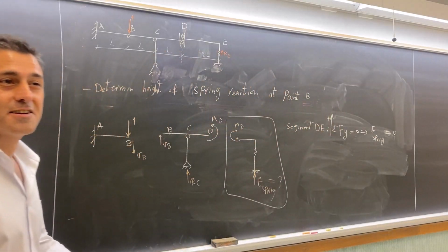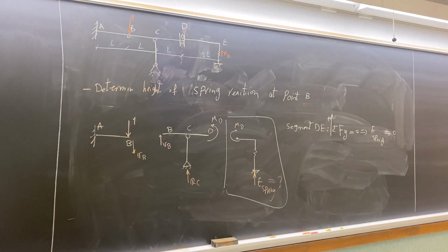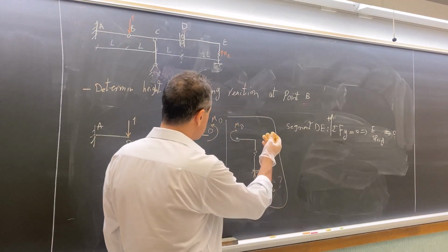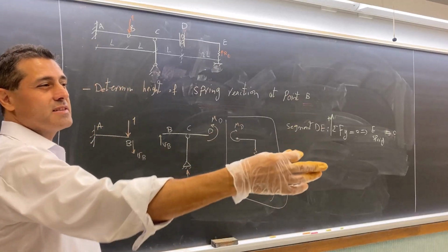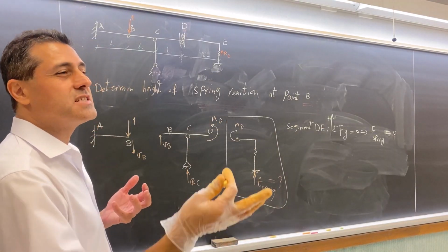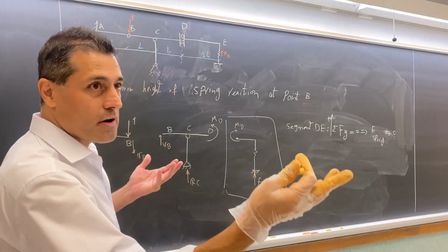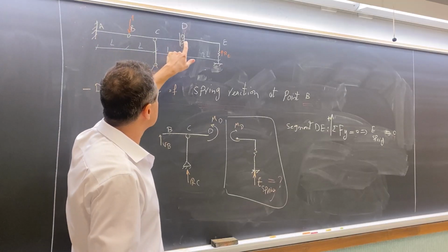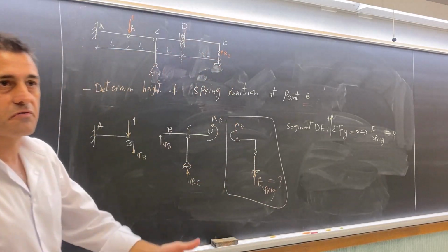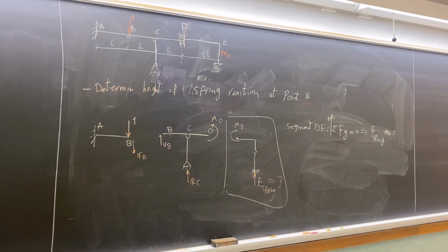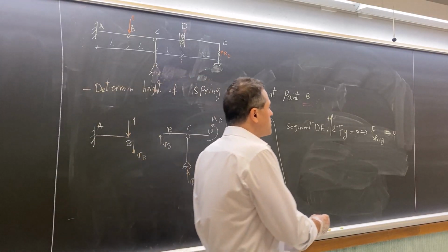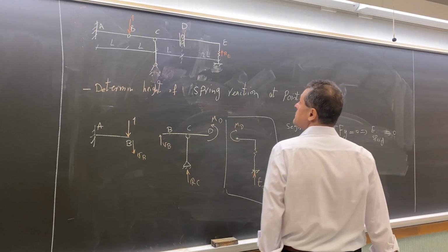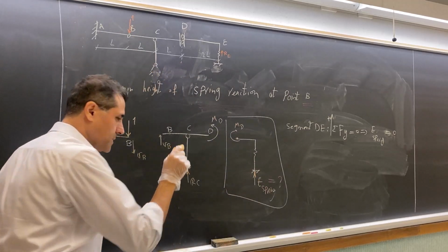That's it. Finished. It's 0. So the amount of spring force or tangent force is 0. I know Clement is trying to understand it based on his feeling, which is fine. You place a unit load here, the load goes here, but nothing will be transferred to this part in terms of feeling. Okay. So basically the height of the influence line for the spring is 0 when you place a unit load at point B. That's it.